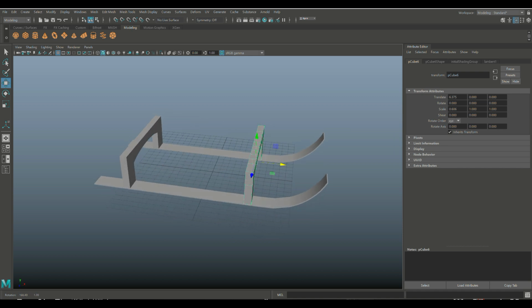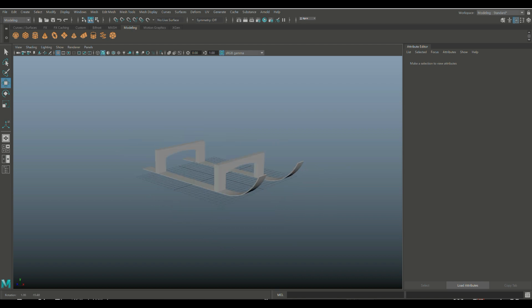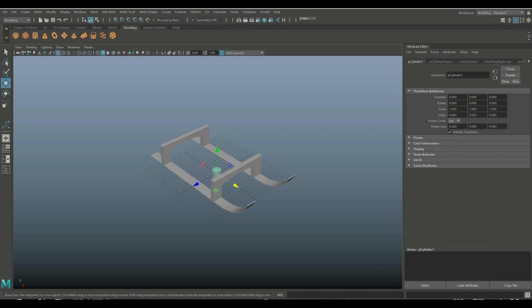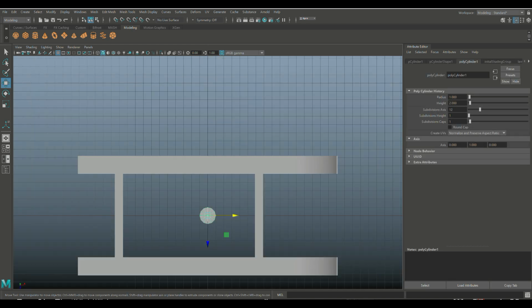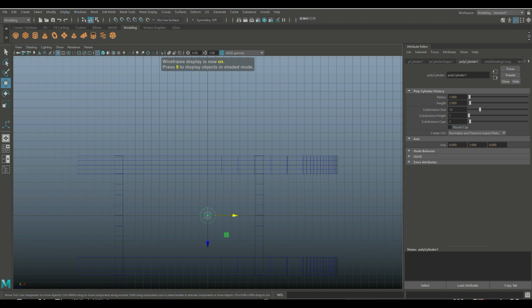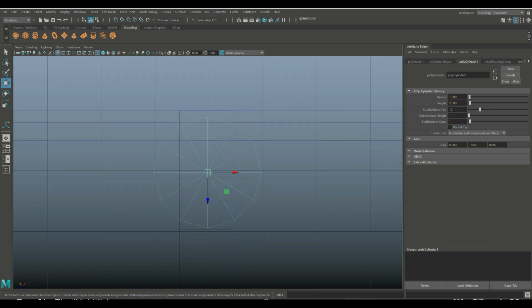Now we need to have a couple of vertical cylinders to hold everything in place. So let's take a cylinder. Let's not go crazy on subdivision here. Let's say, I don't know, 12 should be fine. And caps wise, yeah, we'll leave that in. So I'm gonna jump in here and I'm gonna position this. Let's hit 4. Position this, I would say somewhere around here. After frame, that's where I want to be, right?